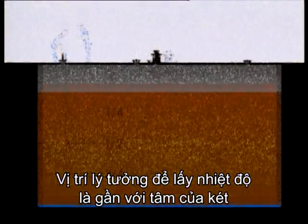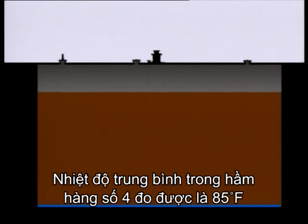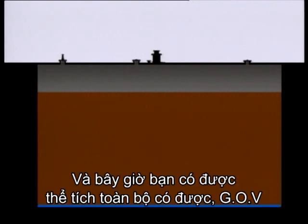The ideal position to measure the temperature is close to the tank centre, but with no vapour control valves here, we have to be content with the temperatures taken at the aft end of the tanks. The average temperature in cargo tank number 4 is found to be 85 degrees Fahrenheit. The volume of the cargo at actual temperatures is the total observed volume, TOV. From this volume, you should deduct eventual free water, sediment, and non-segregated slop. You now have the gross observed volume, GOV.